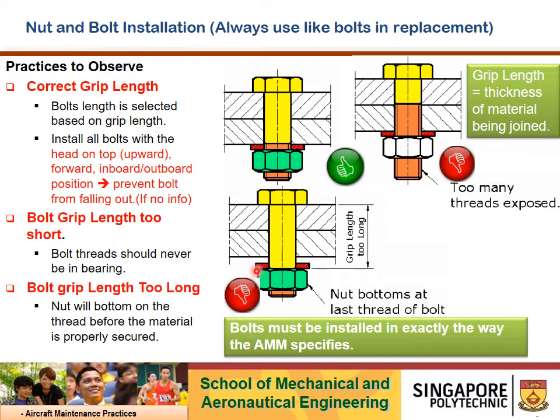In this case, just make sure that you add a washer to ensure there's no locking effect, as per the previous question mentioned. The later part of the slide will talk about how many washers per installation, the maximum washers you can install. By the end of the day, we have to follow the aircraft maintenance manual methods and install the bolts accordingly. If it says that only one washer for this installation, then you really have to use the exact grip length to install the component, right?